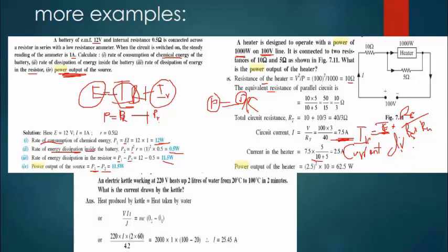We are looking for the current of the heater, but on top stays the other resistor, which is 5, the other one that they are sharing, because here we are looking at a point where current is dividing between this and this. So on top it will stay 5 ohms, as you can see here. Down here the total, 5 plus that, it divides the total current in the circuit of 7.5 amperes.